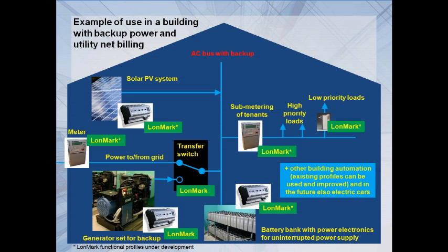If you then use smart controls, where you control both supply side and demand side, as well as the energy storage, you can significantly lower the total investment cost, and you can also increase the security of supply, because low priority loads can be disconnected when needed, and the high priority loads then have a better chance of never going down.